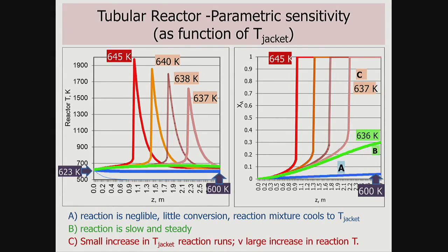And we're setting the reaction temperature to 623 Kelvin, and we've noticed in this particular one, it's flat, but it goes down slightly. So in A, there's a mild reaction, or little reaction, so little conversion, and actually the jacket is cooling the reactor. So it's actually cooled it down to 600, so it's totally safe, but it's not giving us a hell of a lot of conversion.